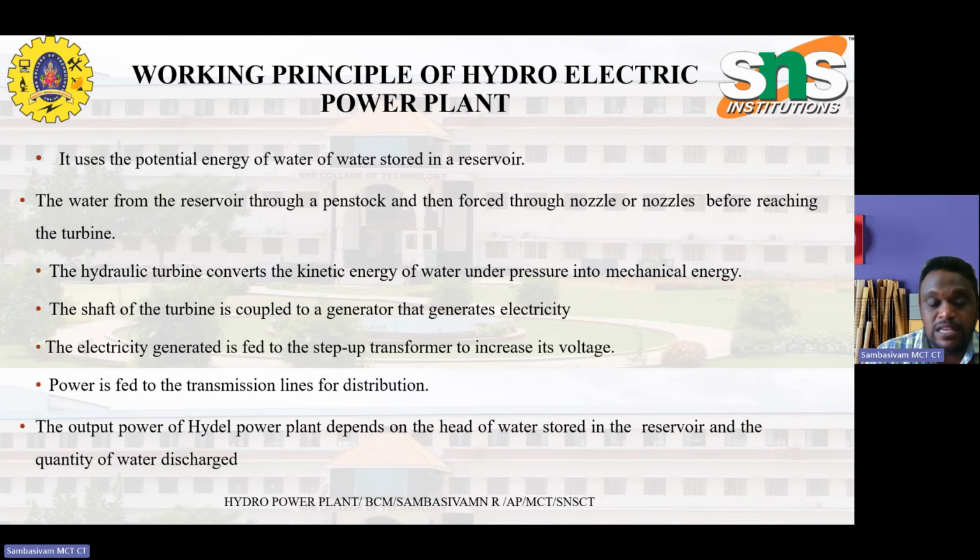Also, one of the major advantages is that the water is available for other use after generation. A river with high water flow and head is a better source of hydropower. The flow rate means the speed of the water when it passes a particular point in the river per second. The head refers to the vertical distance from the top of the slope to the power station. A dam with a large drop is constructed to raise the potential energy of water. The intake is placed at the bottom where the pressure is highest. Water then flows by gravity through the penstock. At this level, the kinetic energy is sufficient to run the turbines.